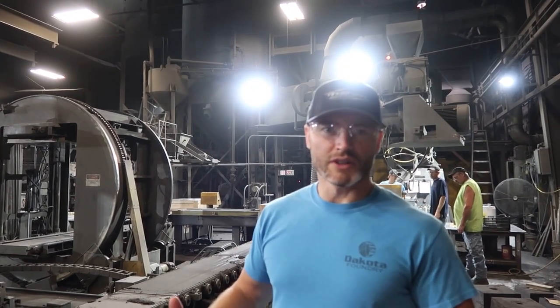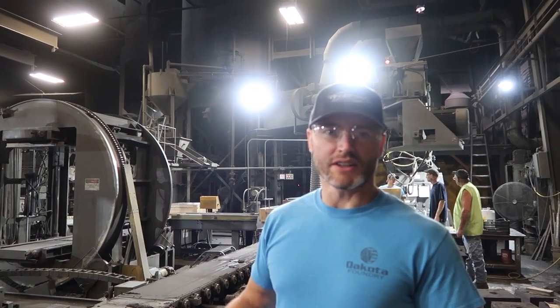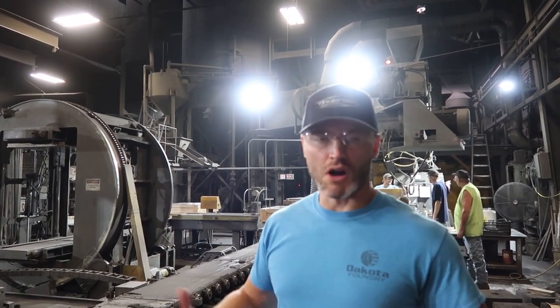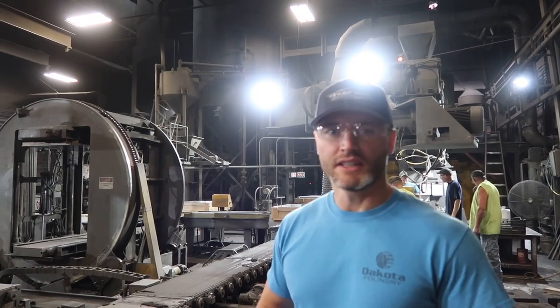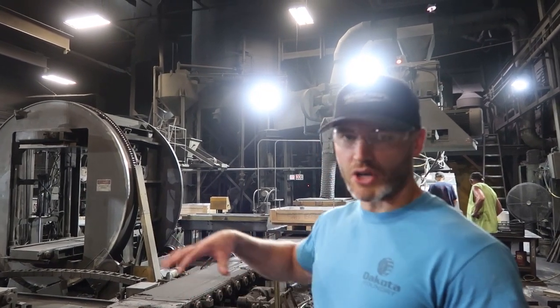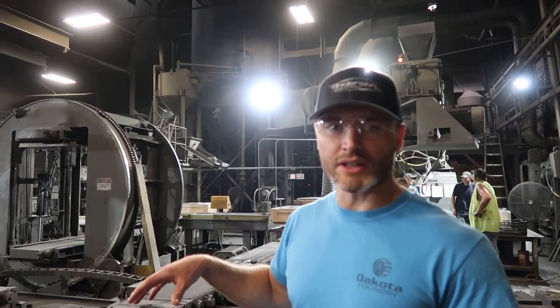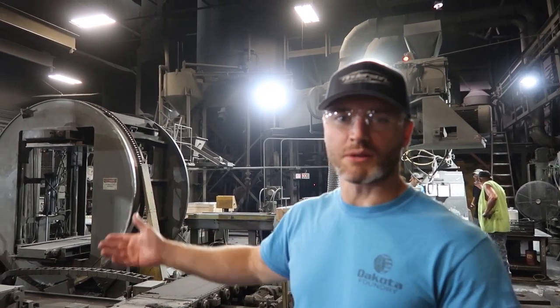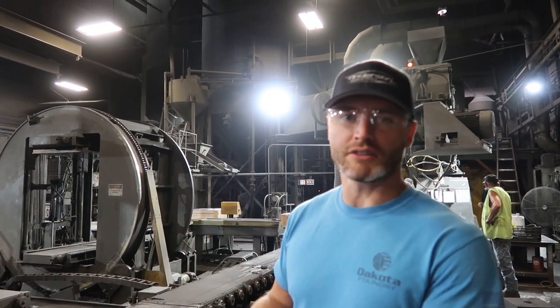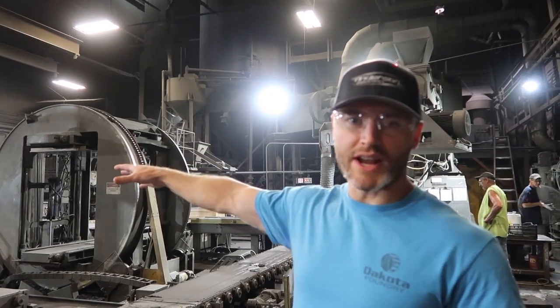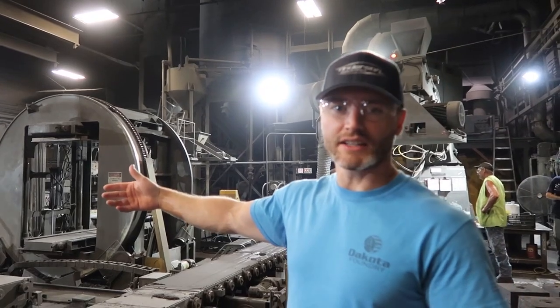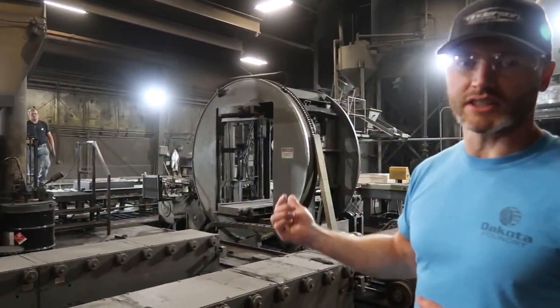This is our rollover line where we're doing the air set or no bake molds. So we do all our larger molds, larger castings on our air set line. So here we have production boxes where all our patterns are mounted in. They run through the rollover system that separates the production pattern from the mold. And the molds go down the cope and drag line to have cores set and be assembled, and then the pattern circulates back to it.